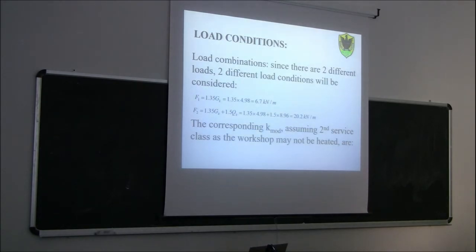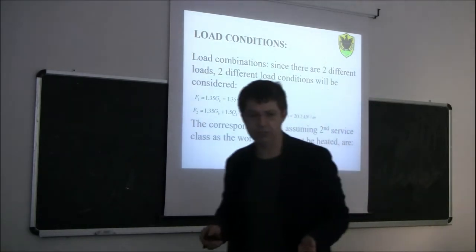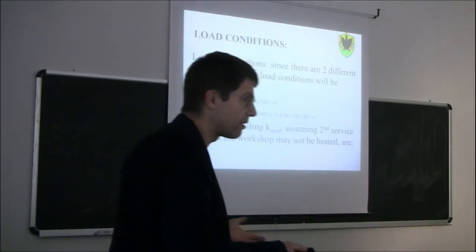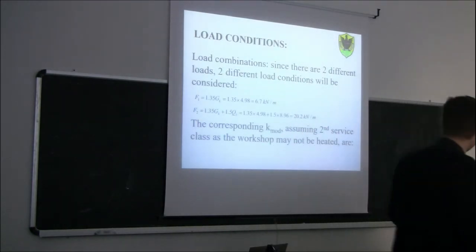So basically our beam will be in indoor condition because it's inside, but in an unheated climate. If you look at the choice of the service classes, you will find that for indoor conditions and an unheated environment, the service class is number 2. Okay, service class 2.